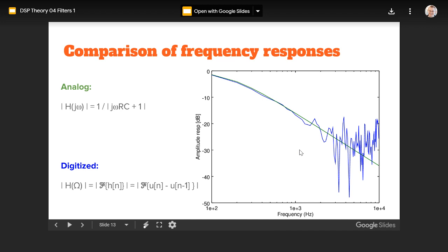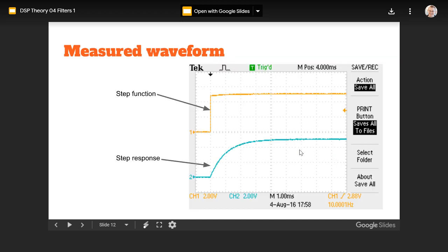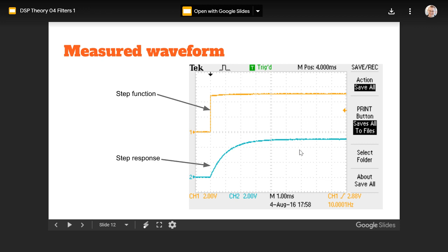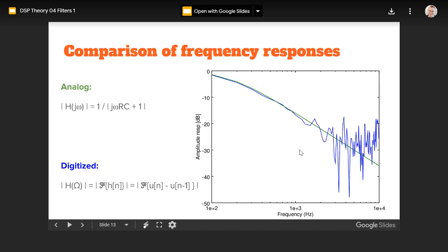That noise floor is only about minus 25 dB, which more or less correlates with the noise you see on this kind of picture. Minus 25 dB is about 1/20th of the signal size, so the noise amplitude is about 1/20th of the signal. Yes, it actually fits pretty well on this picture.